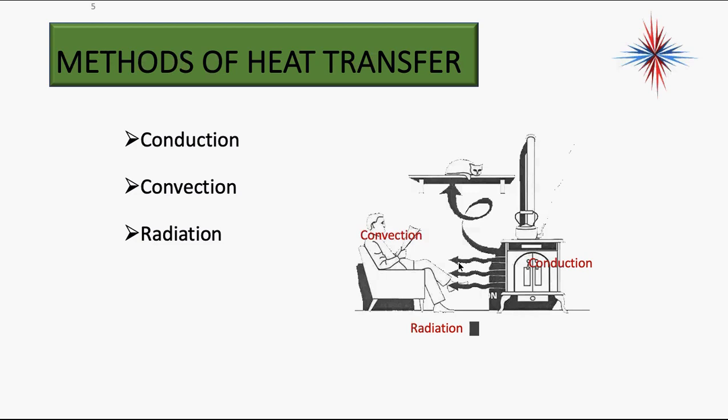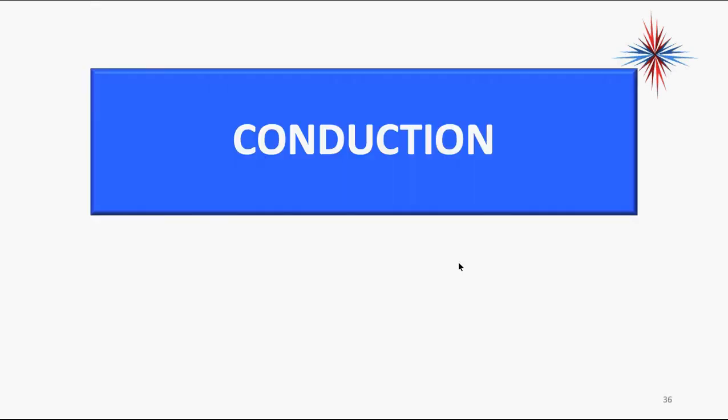By the way, any of you taking state licensing exams, going for certifications or anything like that, you do need to know these. Methods of heat transfer: we have conduction, we have convection, and we have radiation. When we come to our air conditioning courses, you're going to hear me talk about this again. All of those methods of heat transfer are part of our building and design portion. We have to understand how heat flows before we can design our heating systems.